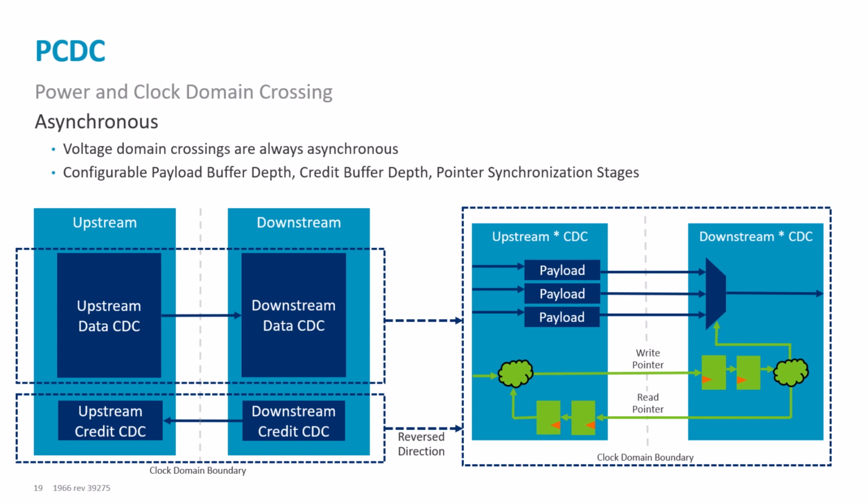An asynchronous clock domain crossing component is required when the relationship between two communicating clock domains is specified as asynchronous. The clock domain crossing component has a FIFO buffer, and you can configure the depth of this buffer. To achieve full throughput, the depth of this asynchronous buffer must be sized appropriately to cover the full credit loop.